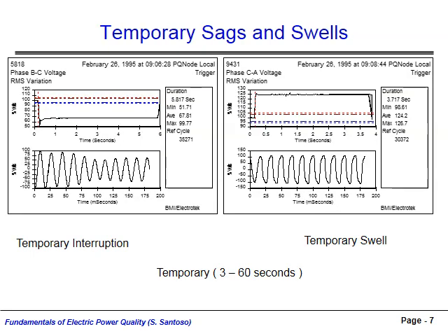These figures represent 2 separate events, the left figure showing a voltage sag lasting 5.8 seconds, the right figure showing a voltage swell occurring about 2 minutes later and lasting for 3.7 seconds. Due to their durations lasting longer than 3 seconds, these disturbances are both classified as temporary.